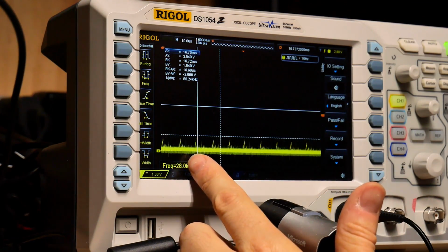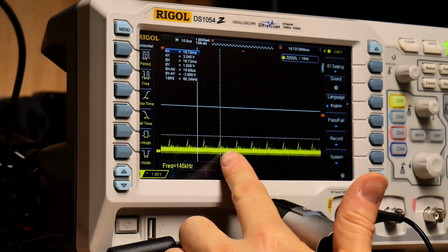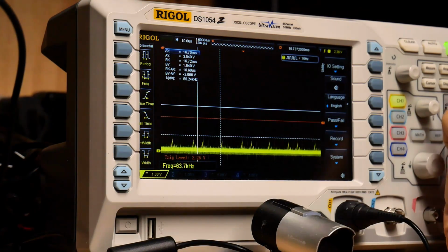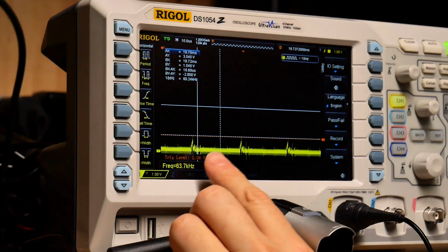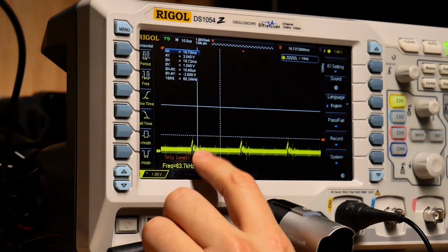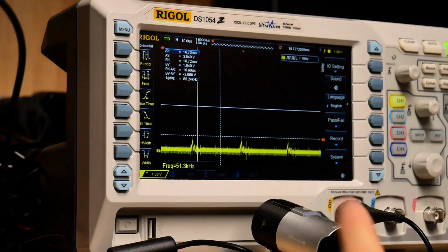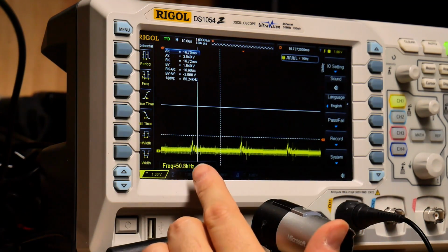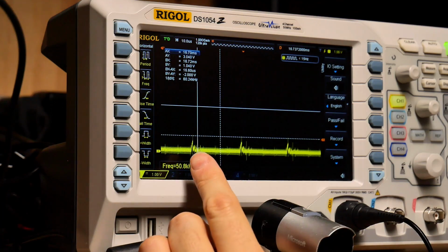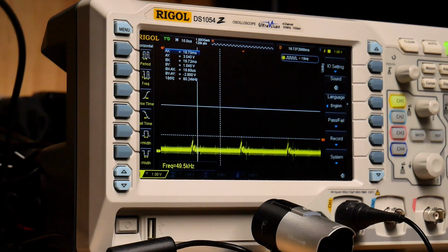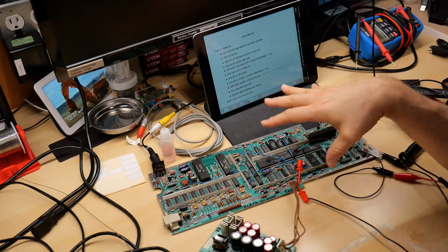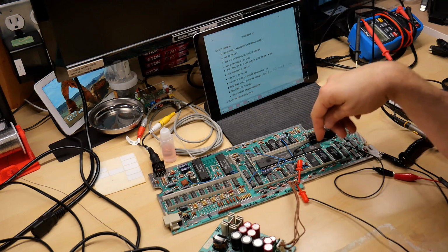This looks exactly like 0, like it's trying to drive it and it can't. In fact, if I move the trigger down, you can see that where the other ones were pulsing up to 5 volts, this thing is being stuck down at 0 volts. And then this line is also screwed up. This is data line 6, it's messed up. And so is data line 7. Wow. So we've definitely identified that there's a fault on this motherboard.